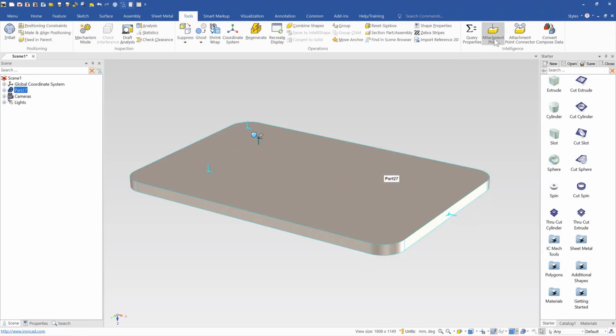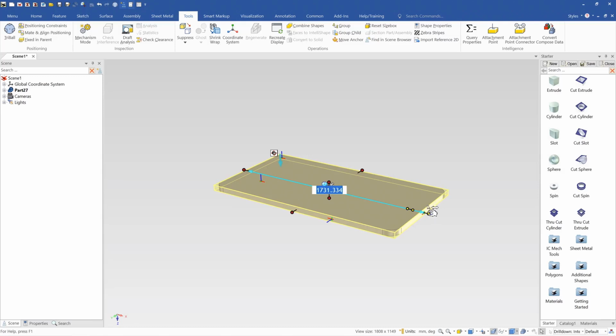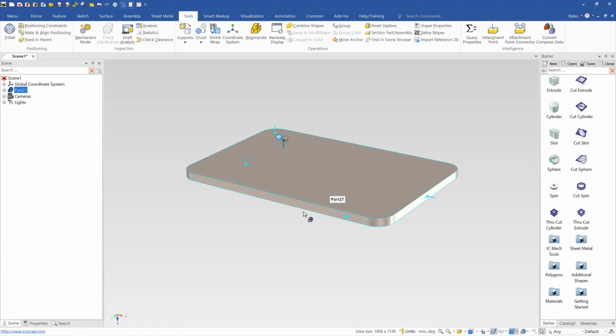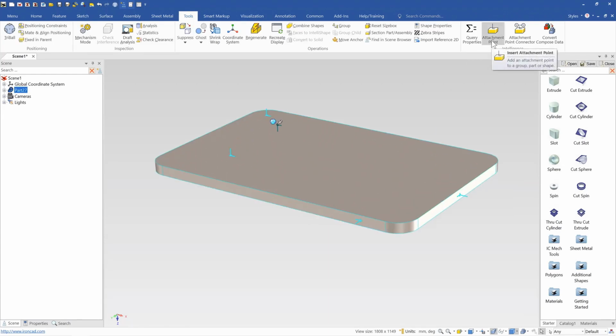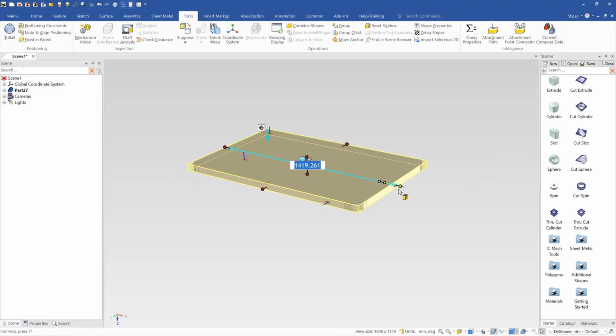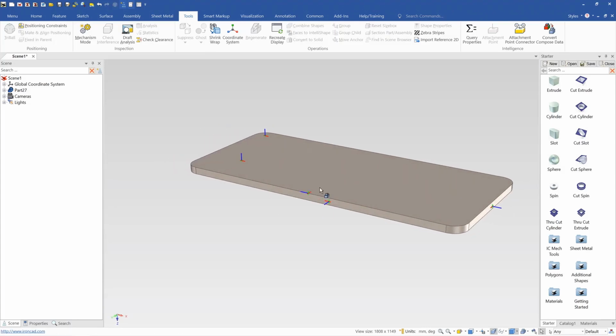And we do the same over here. But it's worth noting, because that's placed in a random position, whilst it'll resize with this face, if you actually resize in this direction, it won't, because it's just placed on that face. So therefore, if you click a point, it will now have two references for the geometry. So for example here, if I choose for this to be at the midpoint here, because I've chosen the midpoint as opposed to just the face, now that'll actually stay at the midpoint as I change this around. As you can see, it's now moving and following the midpoint of that item.